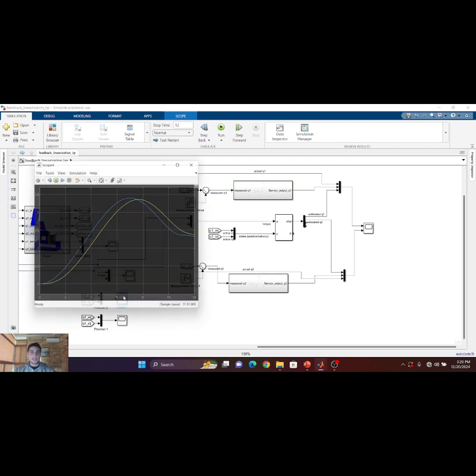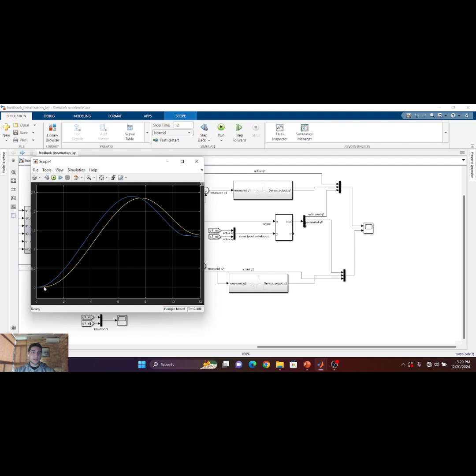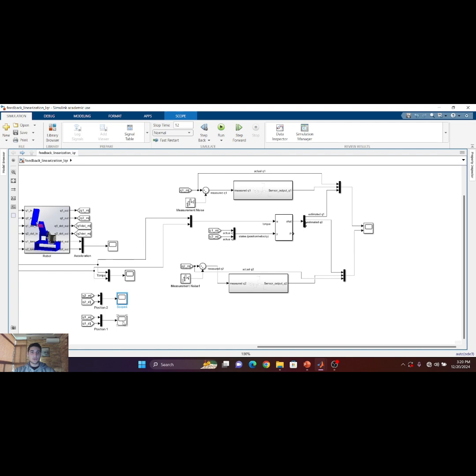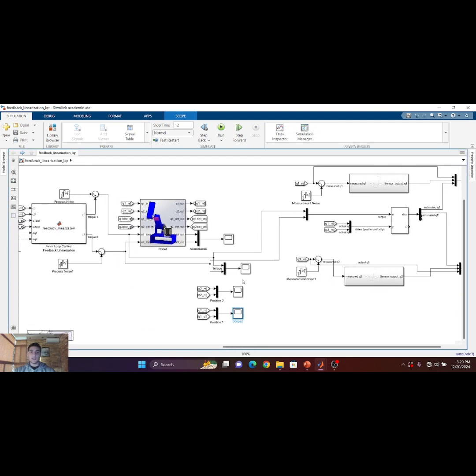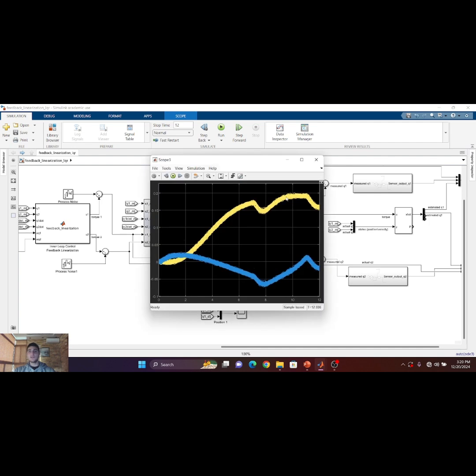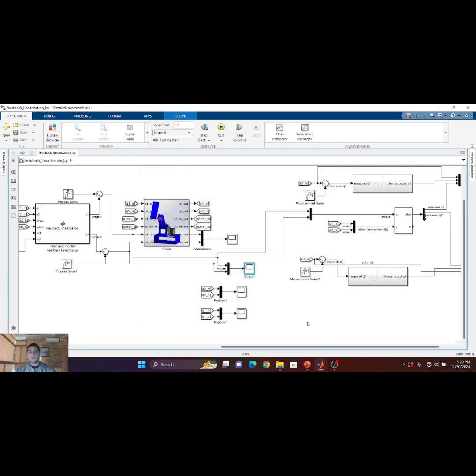As we can see, this is the obtained tracking, where we have tracking for the first joint, the second joint, and the obtained torque. As we can see, 0.2 Newton meter is the maximum value, and this is a reasonable value since our links are of a few grams and they are 3D printed.